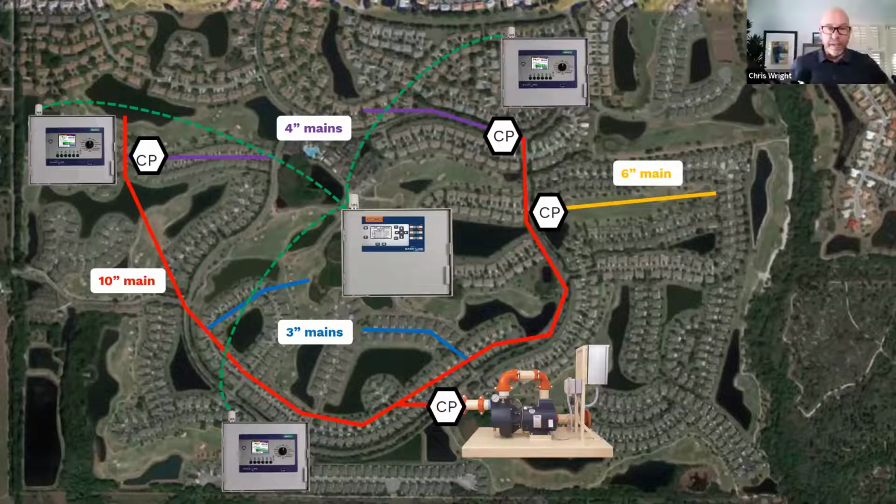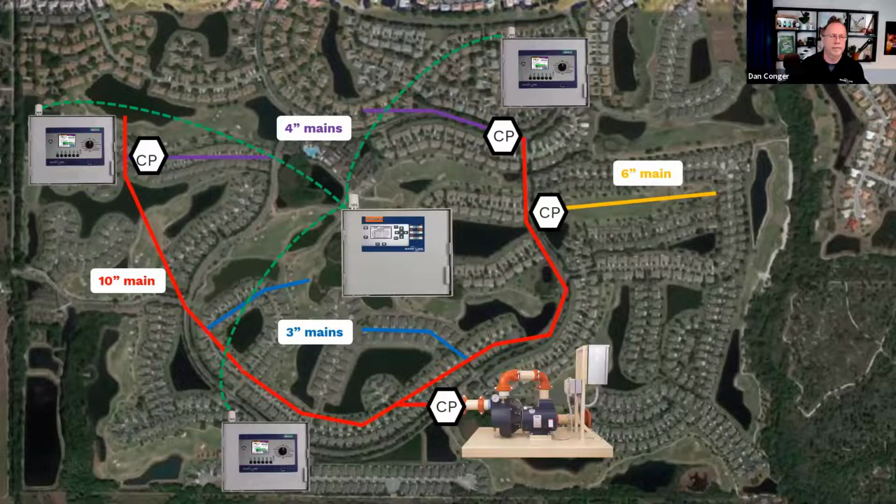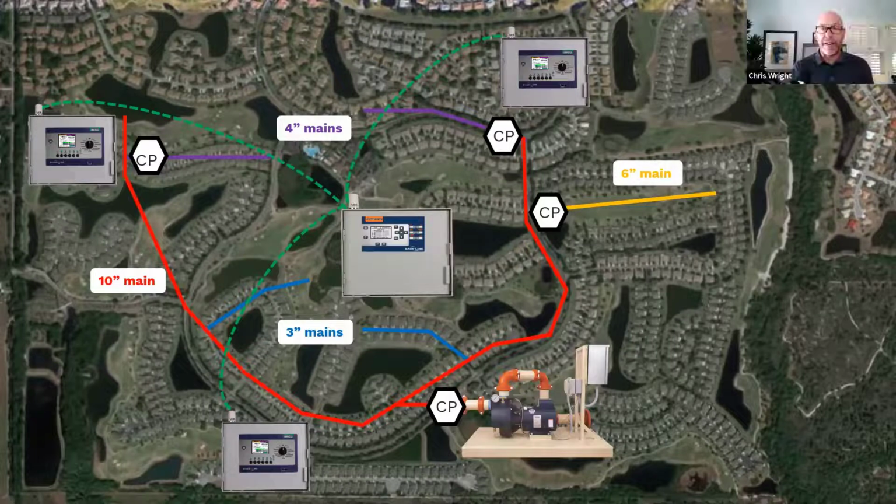Yep. So that's why the FlowStation is able to manage 20 controllers, 20 3200s sharing water sources, but also 40 main lines because of this type of mainline to mainline configuration where you may not have a control point associated with it. It's just a T in the pipe where you go from one pipe size to a smaller pipe size with a different flow characteristic associated with it. Nice. Excellent.